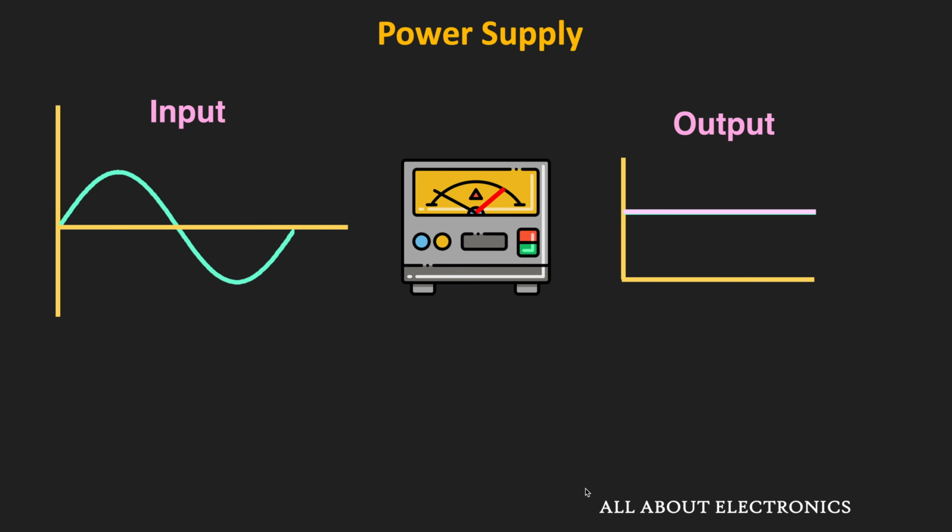But in the actual power supply, if you see, then we do get some output voltage variation because of the change in the line voltage and the load current. So this line regulation and the load regulation shows how well the power supply or the voltage regulators are able to maintain the constant output voltage despite the change in the line voltage or the load current. So one by one, let us understand them in detail and let us also see for the different power supplies and the voltage regulators how these parameters are represented in the different ways.